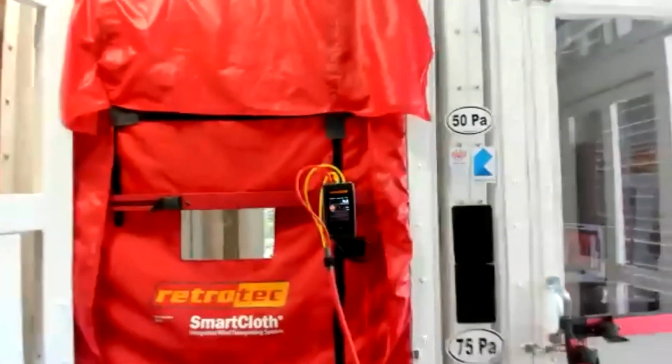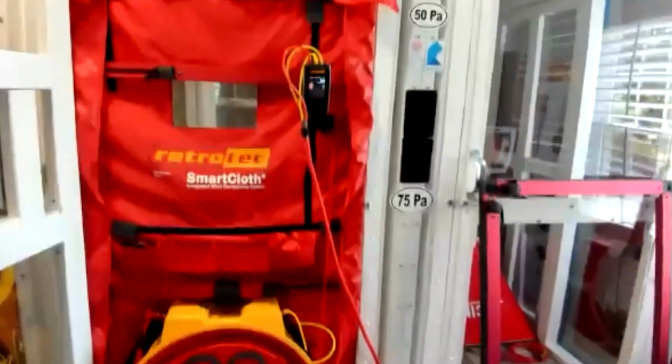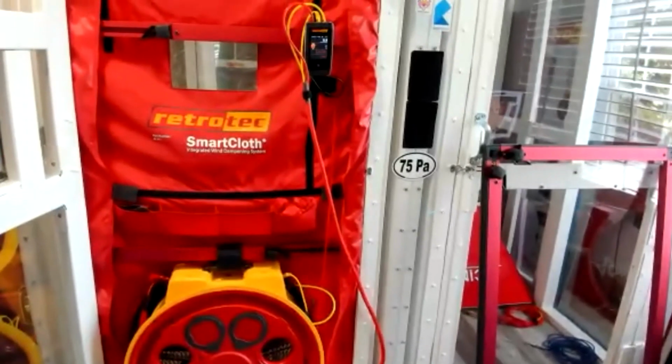And that's how you run a blower door test. That's just what we call a single point test, so we're just running the test to 50 pascals of pressure. And that's it. We can do this manually like this, or we can use that Rcloud app that I was telling you about before to let it collect that data automatically and then save it in a report. So Lee, I'm going to go back to you and see if we have any questions.